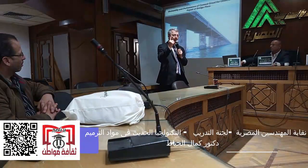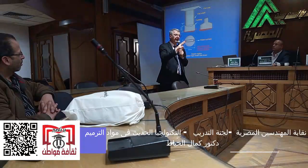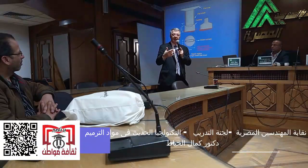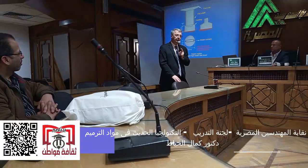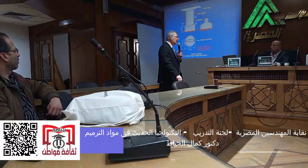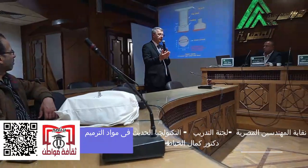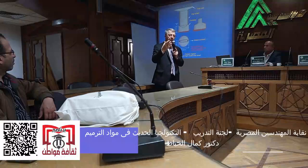We don't only depend on one mechanism of failure. If there's one mechanism of failure, something else kicks in and prevents it from failing. When we do mix design for concrete, we should also use multiple mechanisms, in this case corrosion inhibitor versus thick cover versus proper curing.